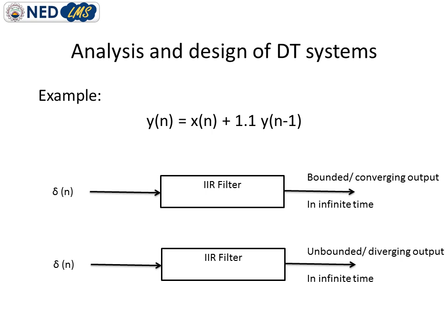Finite impulse response systems are always stable because they do not involve any feedback. But IIR filters, as they depend upon the previous output, can be stable or can be unstable. So this is the disadvantage of an IIR system, that it can be unstable.